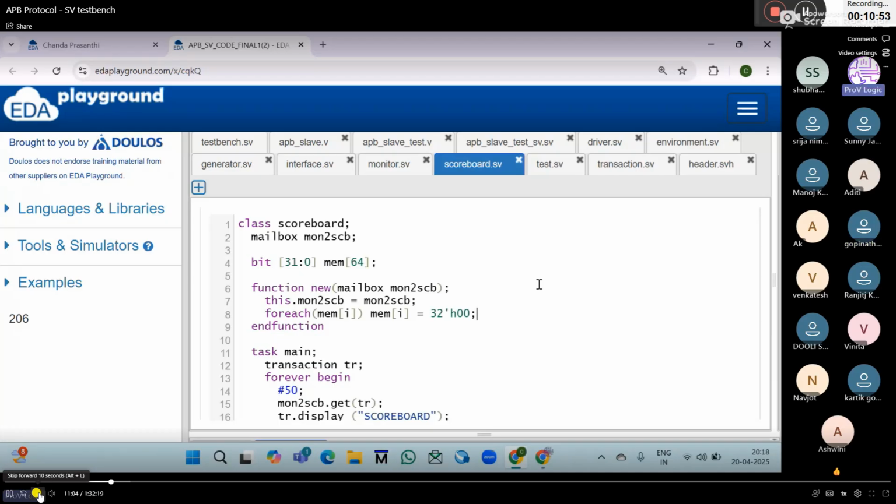Okay, fine. So first of all, the APB RTL design. For UART and I2C, how we designed UART: we took a transmitter block and a receiver block, generated the baud rate, and at the top level connected the transmitter, receiver and baud rate.